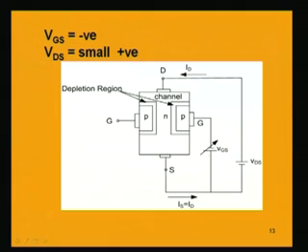As we are having a negative voltage between gate and source, VGS, and by this variable arrow mark we are meaning that we are changing the VGS, that is, the gate to source voltage is varied. Initially it was 0, what we have seen earlier. Now it is increased a little. If we go on increasing, what will happen to the width of the depletion region?